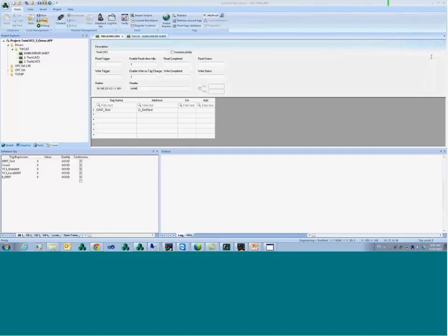So a little bit of troubleshooting here. I got a question: when someone's starting the system, the tags are not always updated between PLC and the InduSoft. So the first communication between InduSoft and the driver, we send a message, we exchange some information with the PLC where I tell the name of all the tags that I want to communicate, and the PLC returns to me pointers or IDs to those tags. And after that, we only talk for those IDs. That's why the communication is fast.